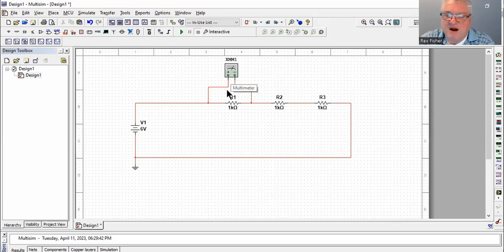If the resistance is very high, then only a trickle of current will flow through that voltmeter. Most of it will continue to flow through the resistor, and you'll get a pretty accurate reading. If you buy a really cheap voltmeter with a low resistance, then a significant amount of current is going to flow through that low resistance. It's going to bypass the 1,000 ohm resistor, and your voltage reading will not be accurate because when the meter's connected, the current through the resistor is different.